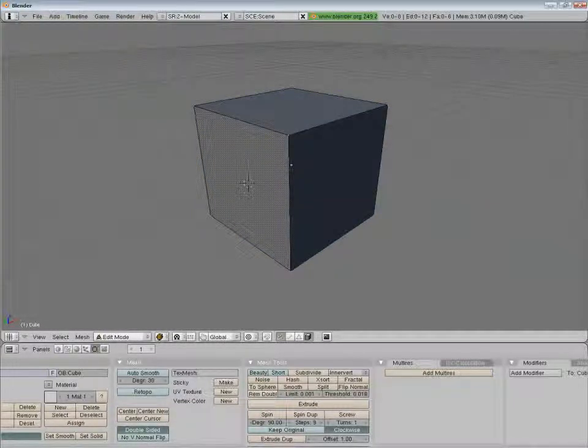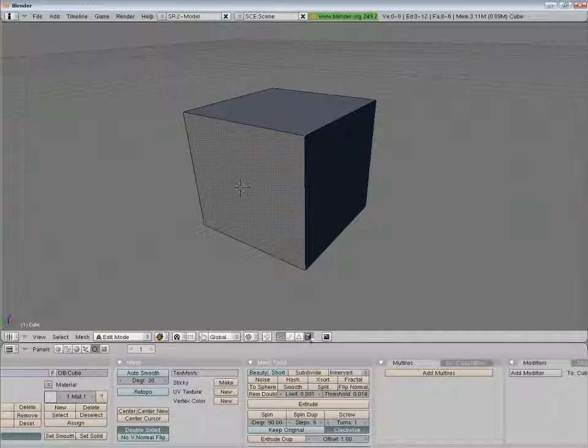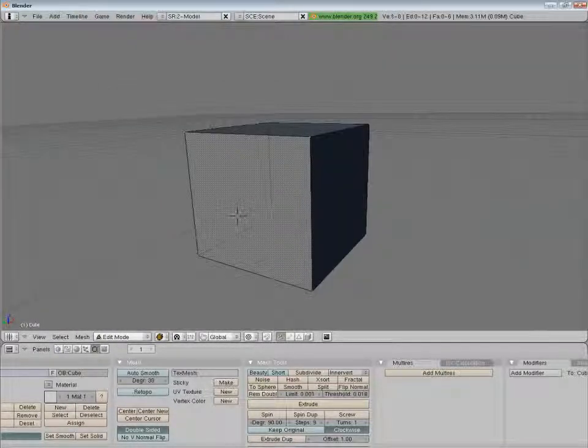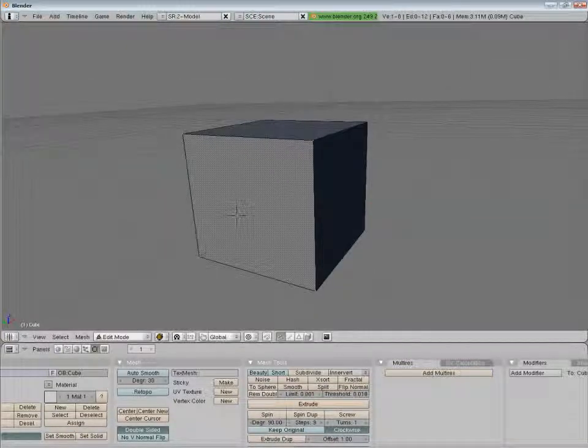And another thing related to display is this button. This makes your object, when in solid view, not wireframe mode, transparent in edit mode. Now you can see, select and manipulate the vertices or edges of faces behind. Next to this are these three select modes. You already know this by now: point select, edge select, and face select mode. And you know these snapping options and the proportional editing options. Now these proportional editing options are only available in edit mode.